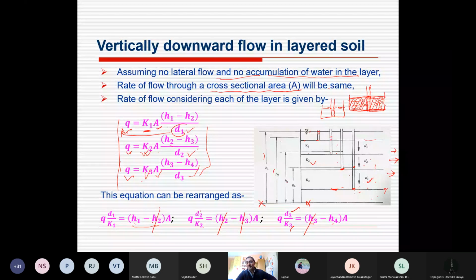What will be the level? It will be the same level of the soil, or it will be less, or it will be more. What is your idea? Less from previous, sir. Less. Why is it less? This is the question. The reason is that it is only the voids which are supplying water, right? And there is a percentage. I told you 30 to 60% is void maximum. So only 30 to 60% of the water reaches this tube and the rest remains in the soil. So it cannot be filled up to the same level.